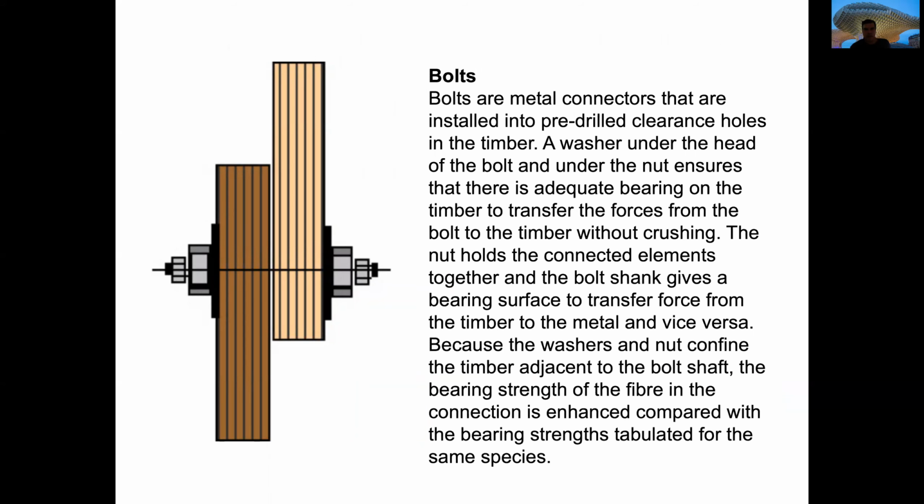Bolts are metal connectors that are installed into a pre-drilled clearance hole in the timber. Usually there is a washer under the head of the bolt and under the nut that will ensure that there is an adequate bearing on the timber and the forces will be transferred.